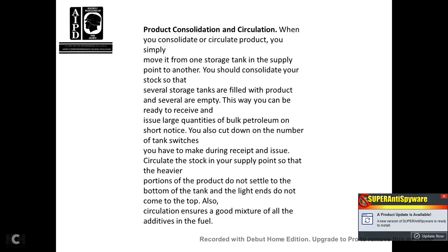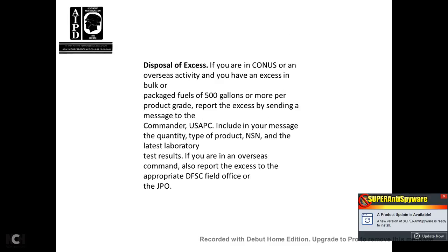You can also cut down on the number of tank switches you have to make during receipt and issue. Circulate the stock in your supply point so that the heavier portions of the product do not settle at the bottom of the tank and the light ends do not come to the top. Circulation also ensures a good mixture of all the additives in the fuel.